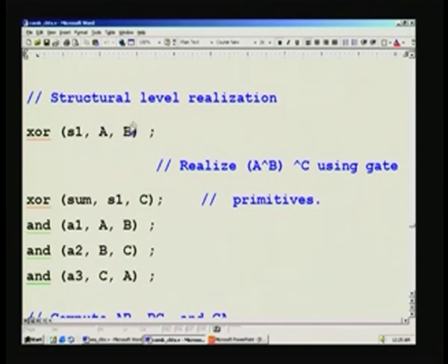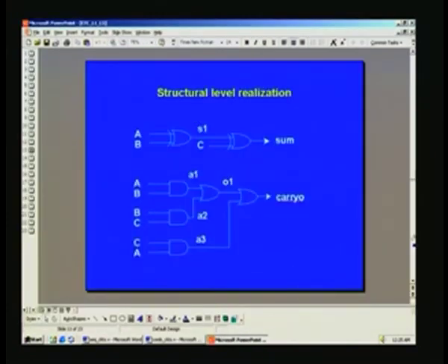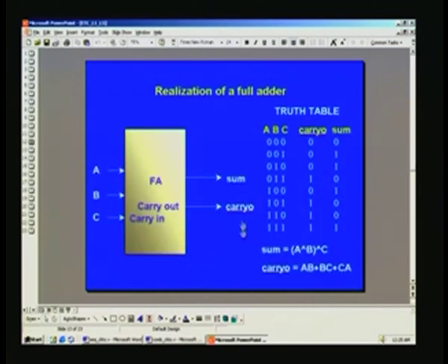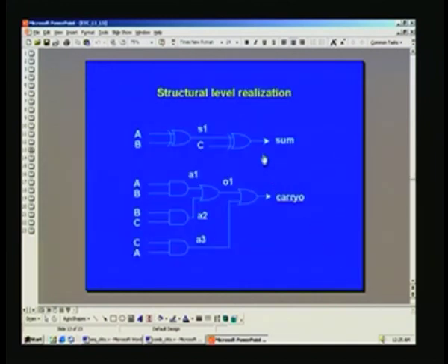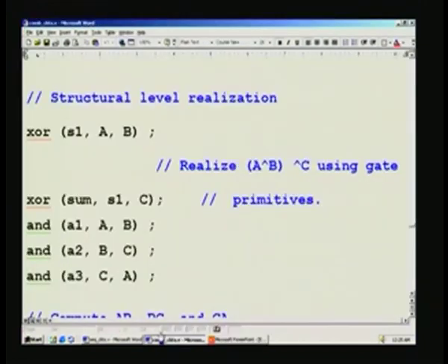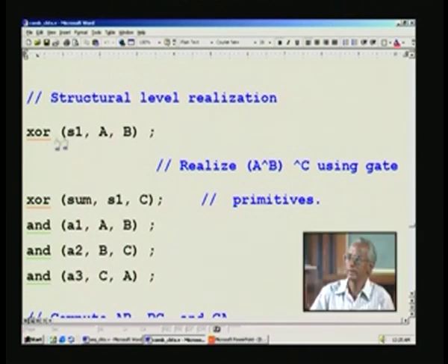You can use a primitive gate, and this is how you use it. And you have seen this here. For the full adder I do not have to explain the sum, carry, and truth table, and this is the final thing. So, in order to implement using gate primitives, whatever you see as the circuit, you can straight away implement. This also has been explained earlier. So, that is what we are doing here. And note that this is an output and these two are inputs for an exclusive OR. And you can, if you want, say U1, which will instantiate it.